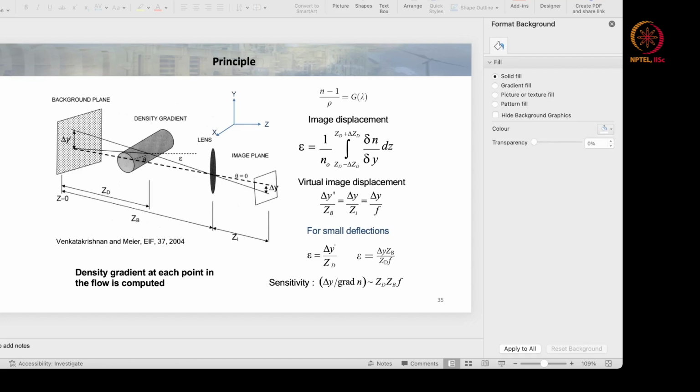This background-oriented Schlieren technique is therefore based on the same relationship between the refractive index of a fluid given by the Gladstone-Dale equation, especially for gaseous media, and this is also sometimes compared with laser speckle density photography. The main purpose is that the reference image is generated by recording the background, which is observed through air at rest. The second step is an additional exposure, which introduces the flow under investigation.